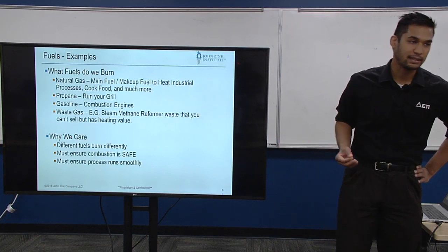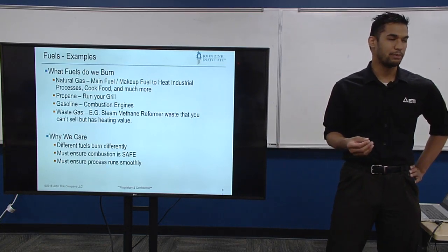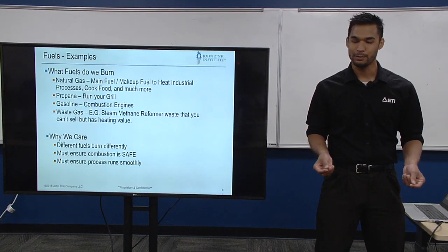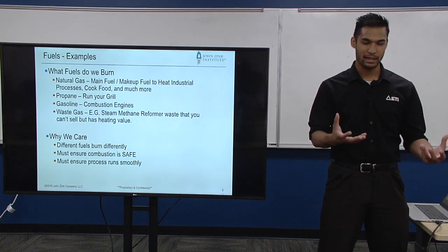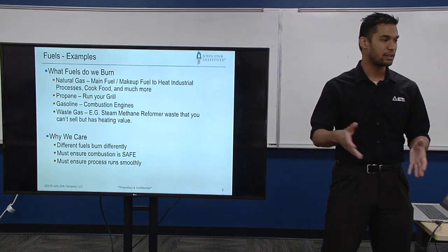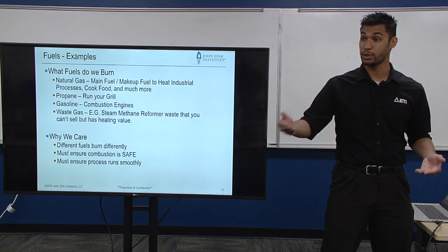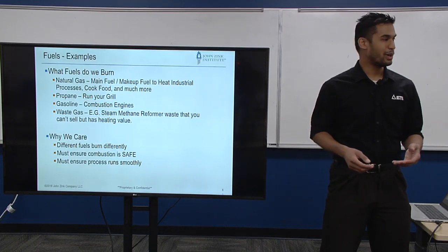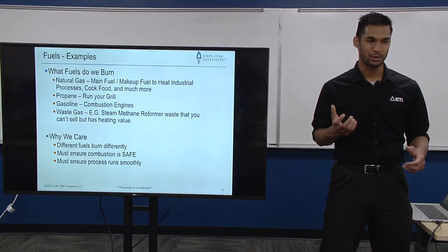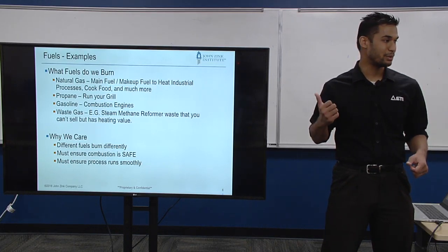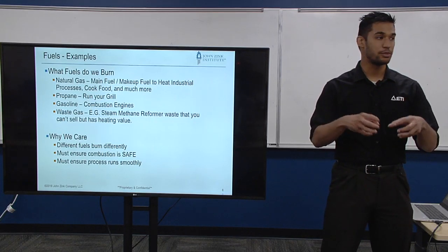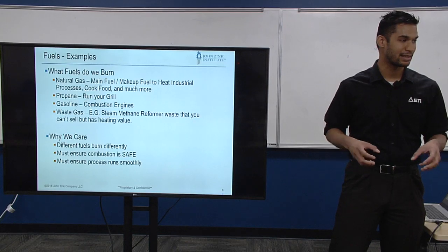And then you have waste gas. Waste gas is really important because sometimes you're running a process and you can't sell everything, right? You have off-spec gas that's not pure enough to sell to the labs or sell to whatever place needs it to continue to run their chemical reactors. You don't want to throw it away. It's really not great economics to just flare it and get rid of it. So you can actually recycle that and capture that heat back by burning it and using that to supply the energy to your process. Okay?